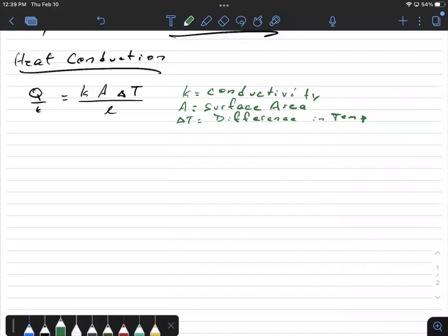And so with a greater difference in temperature, if it's nice and warm on the inside, but extremely cold outside, well, that outside is trying to suck the energy out from the house to warm itself up. And so a greater difference in temperature makes the heat transfer rate much higher. Whereas if the outside temperature and the inside temperature are fairly close together, then there's not really this big pressure trying to pull the energy through.